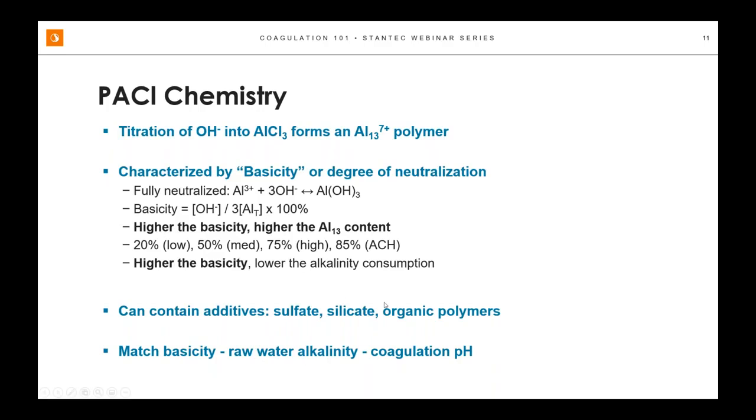However, if you're on the West Coast or somewhere like the Colorado River or the North Saskatchewan River, and you've got a lot of alkalinity, you want something that has some acidity so that it can drop the pH into the range in which these coagulants will work best. So there's a lot of testing involved, and we'll give some examples of how this works in a bit.